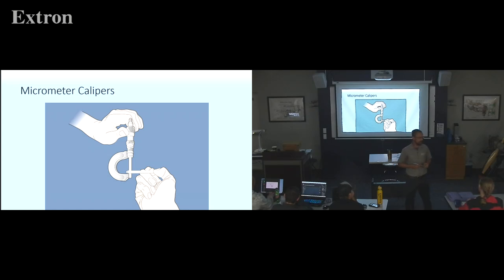Now, if you're doing bolts and nuts, man, bam! I'm going to pull them out, measure them with a vernier caliper about as quick as I can. What makes that more precise? Because this one actually goes to 10,000ths. Vernier caliper usually only goes to hundredths. Sometimes it goes to thousandths. So 4 zeros. Tenths, hundredths, thousandths, 10,000ths. And that goes to 10,000. And this one is a fine tuning.